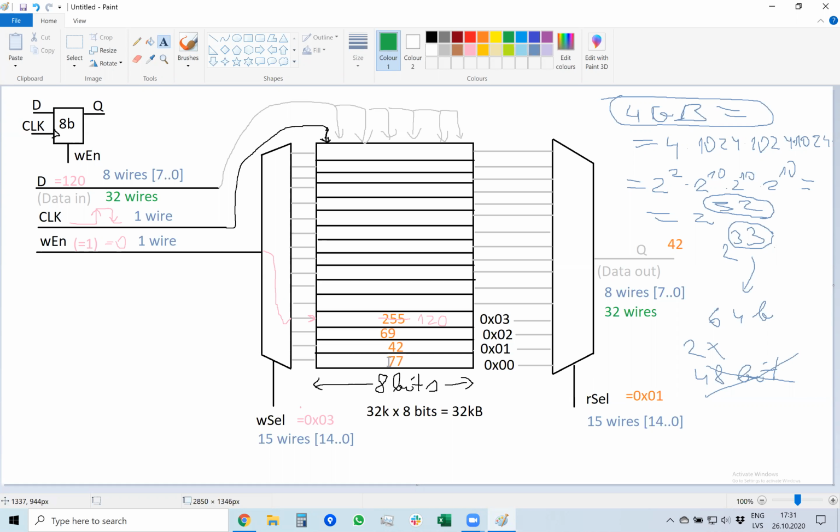Okay, so you can store, for example, one 8-bit number in any address because you select with read select any address and it will output you the number. But 16-bit numbers can only be stored in addresses that follow one another, and the bottom address starts with a number that divides by 2. So for example, a 16-bit number can be written in these 2 memory cells, but it cannot be written in the memory cells 1 and 2 because the processor cannot read them in such way.